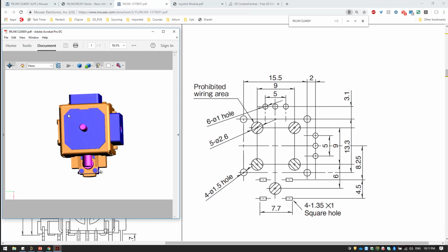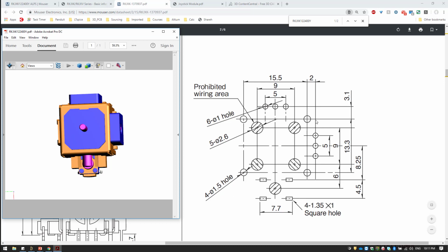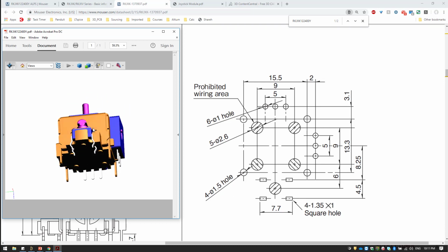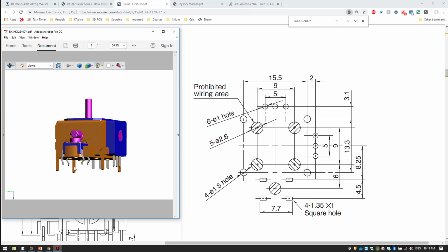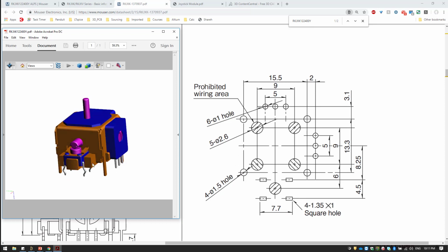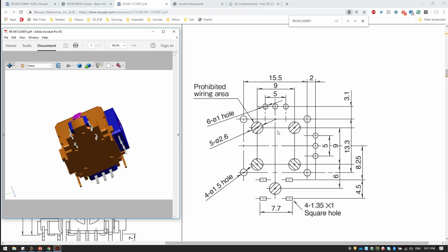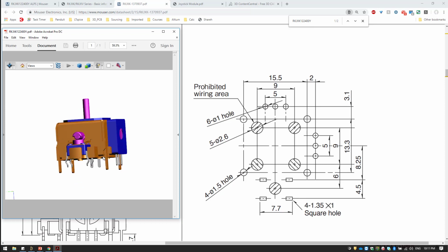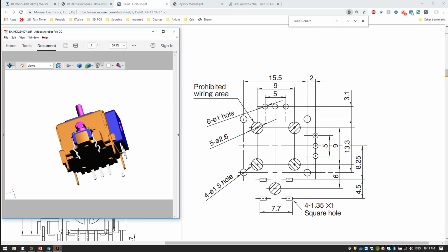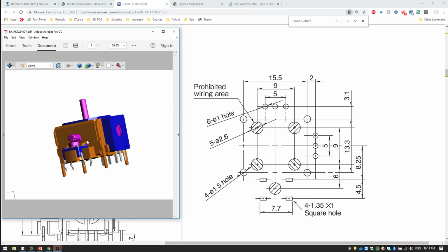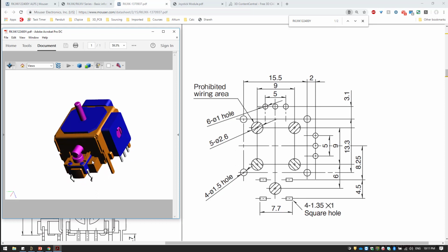If you look at the top view, this is exactly what you are looking for. If you turn it like that, these are the four pins, 1, 2, 3, 4, and here you have this feature, and these are just holes, 1, 2, 3, 4. You just make holes that are not plated, so there is no copper inside these holes, just the fiber. You drill through the PCB and there is no copper inside. It's called non-plated holes. The other one with copper, they are called plated holes.